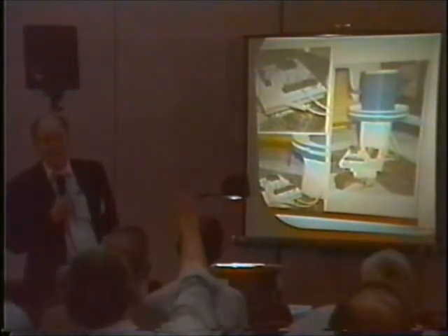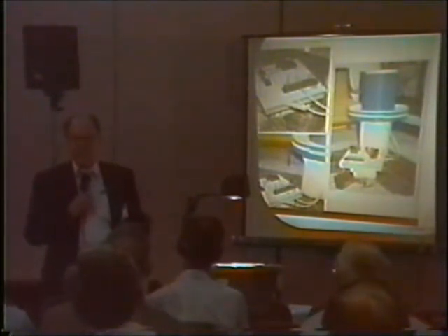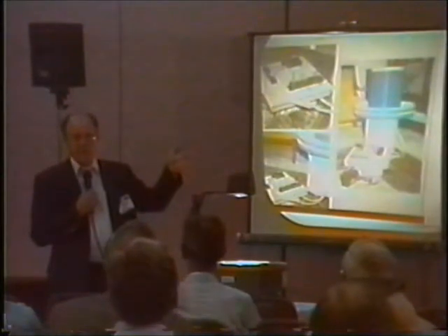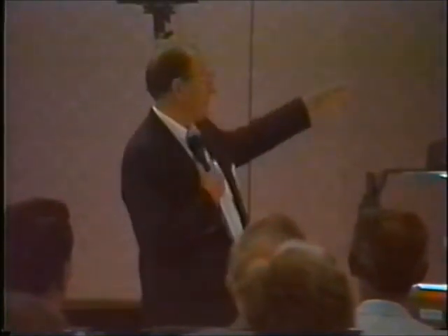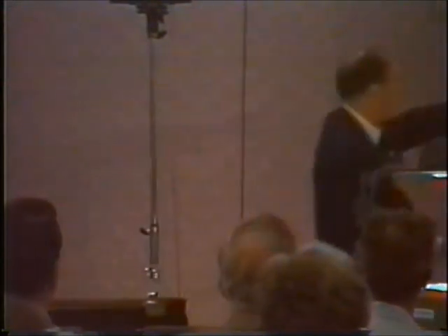Yes? What kind of wire are you using out there? Well, what you have to watch out for is the voltage difference between two wires. So if there's 750 volts on one wire, between the two wires you would have 1500 volts possibility that you could play with, so that you could have a differential of voltage as you go up of 1500 volts, and you'd probably want to stay at about 1000, which would give you a 500 volt safety factor. In this case, there's 130 turns on that thing, so it'd be 130 times your 1000, say, if that's what you put on each turn of your L1 coil, which would be this one.